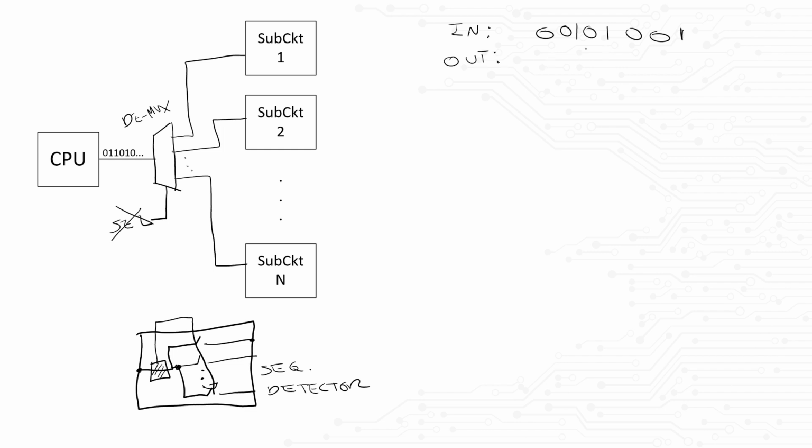I cannot possibly have a valid sequence until I have 4 bits, so I know during the first 3 bits, the output of my FSM will be 0. At the 4th bit, I can check my sequence. Since it is not what I'm expecting, the output will also be 0. Also, since the FSM is meant to be overlapping, I look at the previous 3 bits plus the incoming one until it matches my sequence, like so. You can always check with the interviewer at this point to make sure you're on the right track.